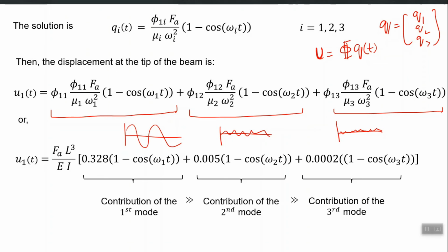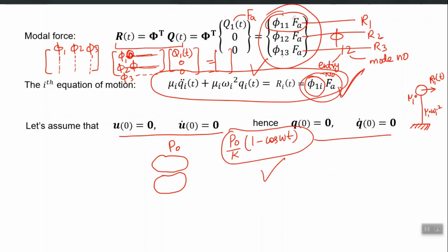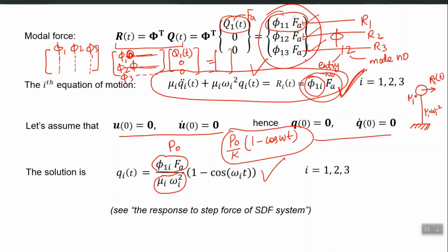The only requirement is that you have the solution of that single degree of freedom system, this equation. Currently I gave a classical loading, which is the impulse loading, so I already had the response available for it. But if, for example, I give this loading as a random loading, then you will have 3 random loadings R1, R2, R3. Then the solution of each modal SDF system will require either the Duhamel integral or step-by-step direct integration, but the overall method will remain the same, right.